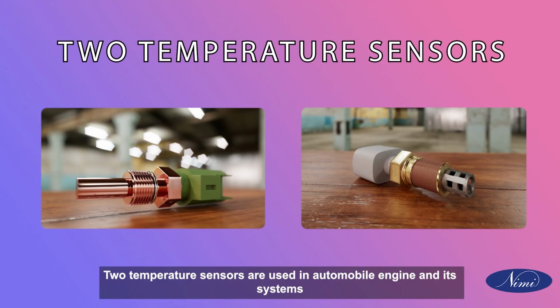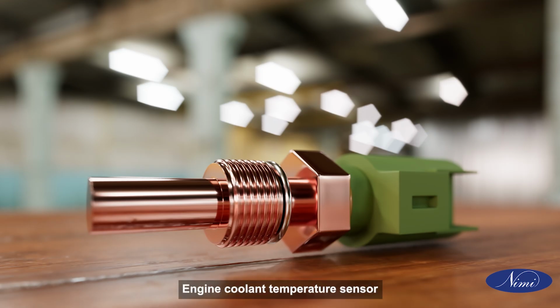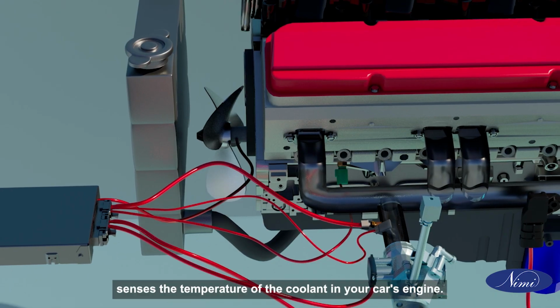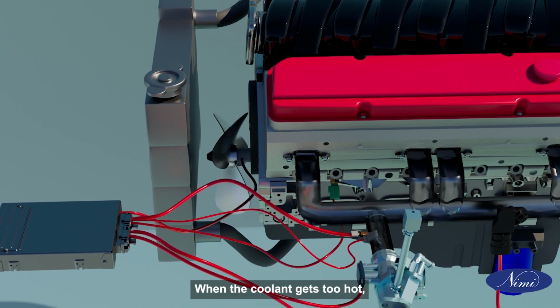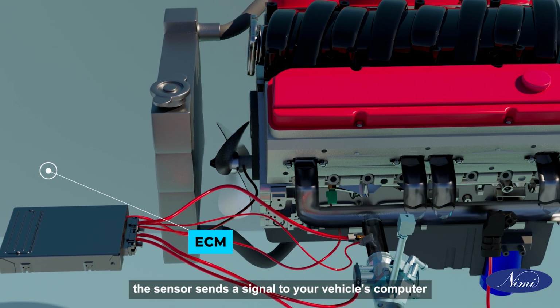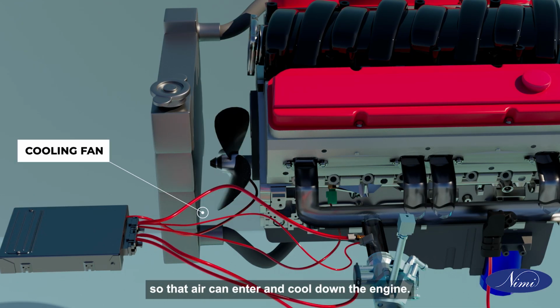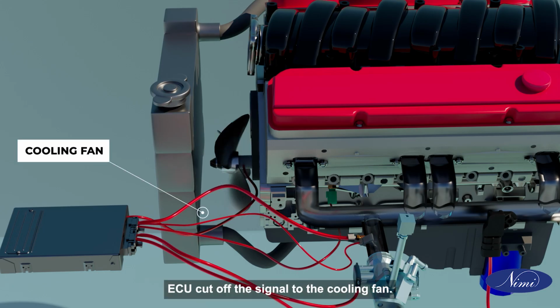Temperature sensor. Two temperature sensors are used in an automobile engine and its systems. Engine coolant temperature sensor. The engine coolant temperature sensor senses the temperature of the coolant in your car's engine. When the coolant gets too hot, the sensor sends a signal to your vehicle's computer, which starts to rotate the cooling fan so that air can enter and cool down the engine. When the coolant temperature returns to normal, the ECU cuts off the signal to the cooling fan.